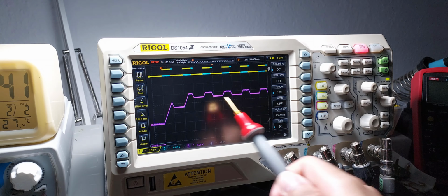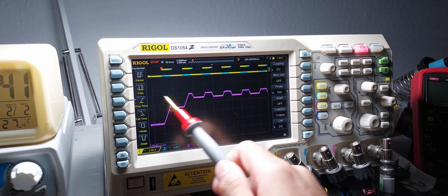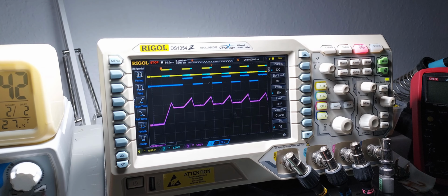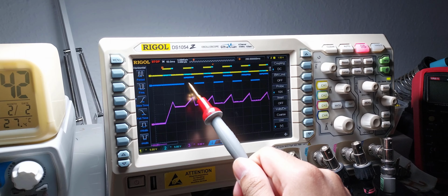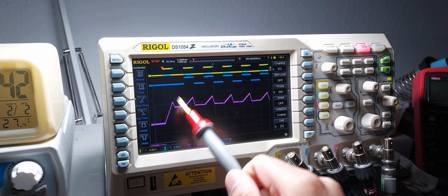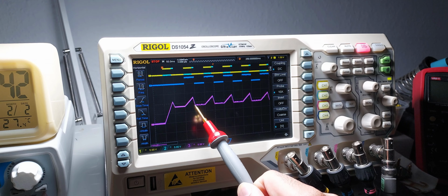If no feedback was applied, the integrator would simply saturate during the next PWM cycle, so every PWM cycle after the first, the output of the sample and hold circuit is fed back into the integrator, skewing the slopes so it starts and ends at the same voltage, which is proportional to the duty cycle.